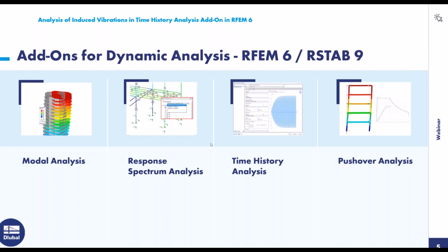Here you can, of course, choose a response spectra according to a design code, for example, the Eurocode or the US code or some other codes, whatever you want to use. You can also create your own response spectra, maybe also out of accelerograms if you want to do this, and then the program will calculate for each FE mesh point internally an equivalent earthquake load, and then you will get at the end, of course, the internal forces for the directions and also the combined reactions of the whole structure.